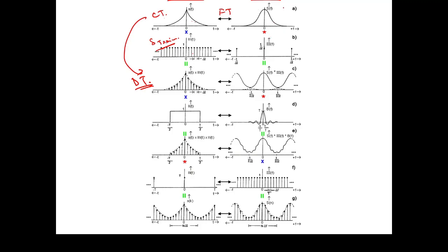If you look into the frequency domain, we have the frequency component of the signal. The Fourier transform of an impulse train is also an impulse train. It would be something like this. We are giving multiplication over here. As soon as we get this discrete time signal and perform the Fourier transform, what we get is frequency components which are repeating themselves.